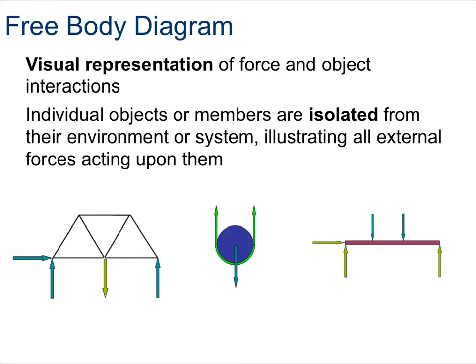A free body diagram simply isolates an object from its environment or system and symbolically examines all the forces acting on that particular object. Thus, a free body diagram should be drawn completely isolated from all other objects. We free the body from its system. This allows engineers to focus on the forces acting upon that object. From the free body diagram, engineers can also develop equations which can be used to describe equilibrium, motion, momentum, strength, and many other physical properties.